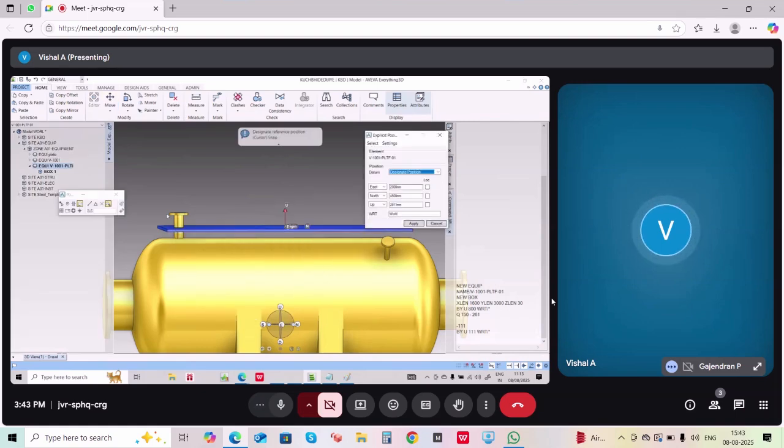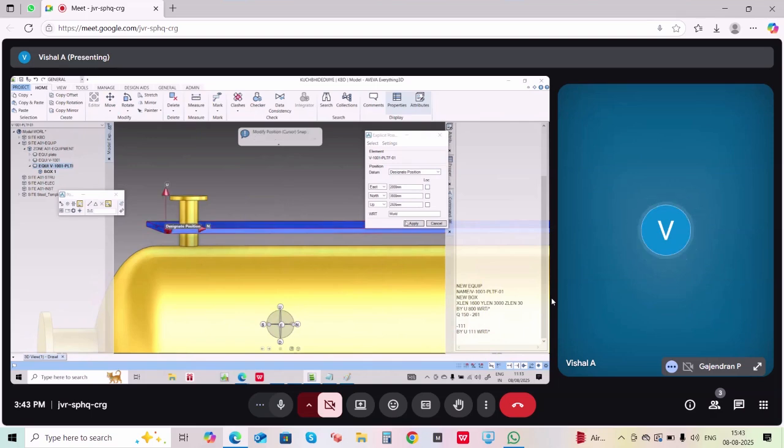So designated point, and then I will go and select this point. So what is the up value? The up value is 2926. Either you can make this 2950, or you can make this 3000. When they calculate the top of platform or top of grating, the value should be a round figure. So if I want to add here, for example 3000 minus 2926, I need to move 74 mm up. If I move 74 mm here, what will happen? This value will be reduced.